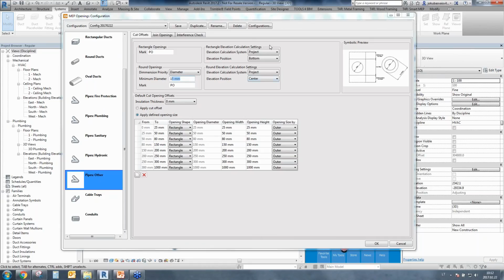What's more, we have special elevation calculations, as our families are just generic models, phase-based elements, and then we place those elements to the wall. They do not have an elevation parameter at all, so we need to recalculate the elevation ourselves.